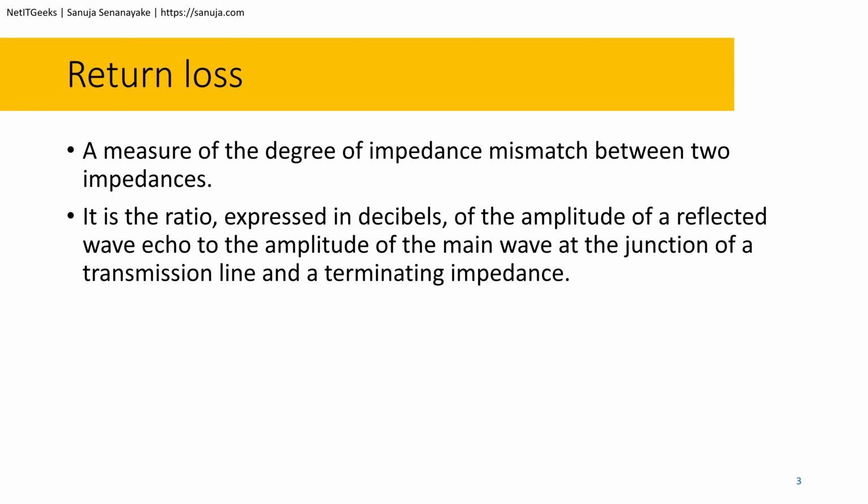So poorly constructed cables with irregular twisting or inconsistent insulation can result in greater impedance variations, leading to increased return loss. Improperly installed or substandard connectors can also increase the impedance. Loose or untwisted terminations are common issues with return loss as well.